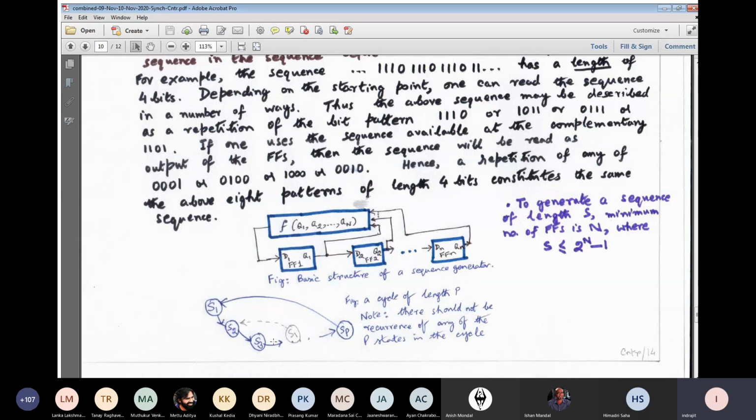So it is mandatory that if you find, while trying to design the circuit, that some state occurs more than once, then we have to keep on increasing the number of flip-flops, right? Why do we say this? Because only by increasing the number of flip-flops can you increase the length of the sequence. So we do not want a subsequence. So increase the length of the sequence, and hence we get finally the desired sequence. Clear? Let me try out with some examples.